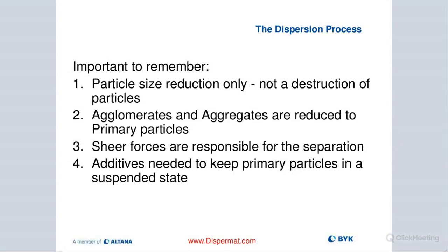So important here is that we are not really trying to destroy particles, right? We're not crushing them or anything like that. We're really trying to break up the binding forces, these Van der Waals forces that are holding these particles together, and then turning these larger clusters, these agglomerates, into aggregates.